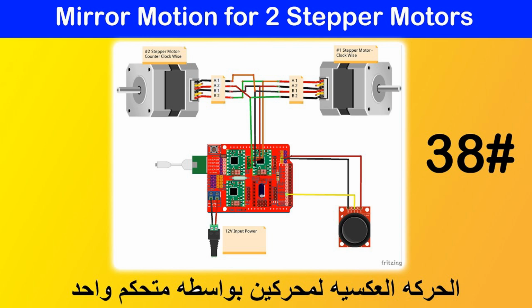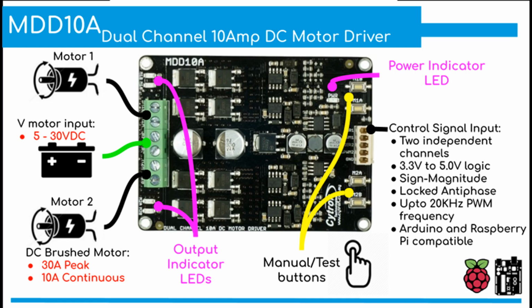5. Types of universal motor drivers. Universal motor drivers can vary in complexity based on the features they offer and the type of motor control required. Some of the common types include A. Basic universal motor drivers. These drivers provide basic speed and direction control, typically using simple voltage control or low-complexity PWM circuits. Features: simple speed adjustment, forward/reverse direction control, basic overcurrent protection. Applications: small household appliances like mixers, vacuum cleaners, or portable fans. Examples: low-cost motor drivers used in small power tools and home appliances.